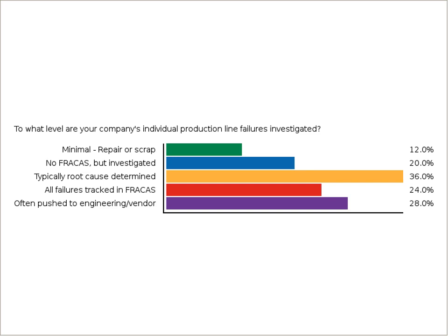FRACAS can be a personnel-intensive operation. It requires understanding of failures, and that takes head-scratching and time. But the value that you get from it far exceeds what you put into it. It's always a positive return when you can get a failure mode, understand it, and eliminate it.